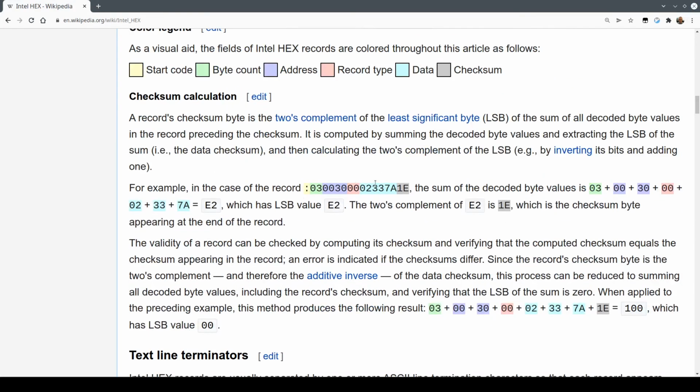So when it's colored like this, colon 3 is the number of bytes, and here it is, number of data bytes, 1, 2, 3. This is the address. This is hex 0030. The record type is a 0, which is just data, and then the sum. The checksum is actually quite easy.